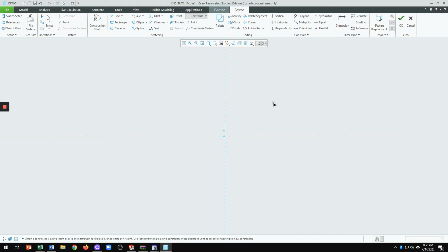Still, you see that the x is attached to the cursor. That means the command that you have invoked is still active. If you want to terminate that command, we just click on the middle or wheel button on the mouse, so the middle.